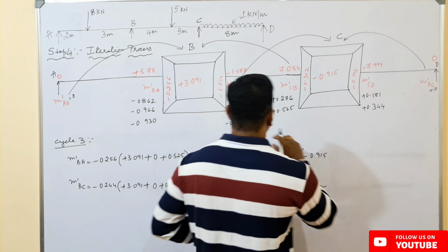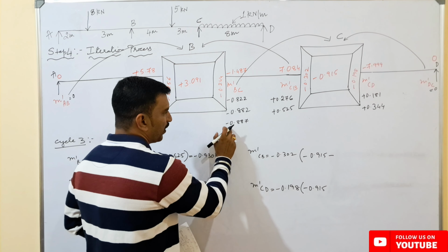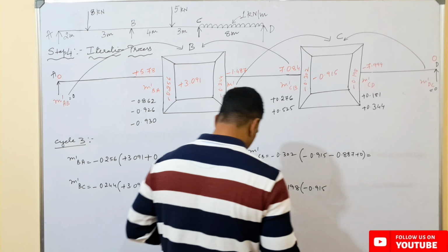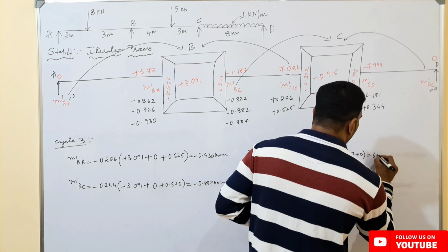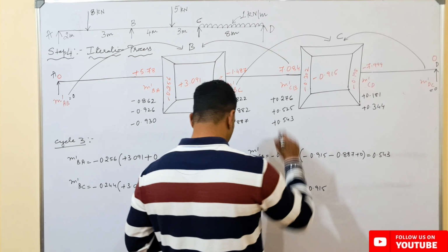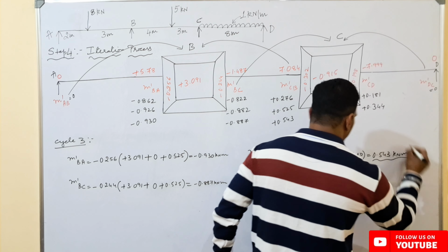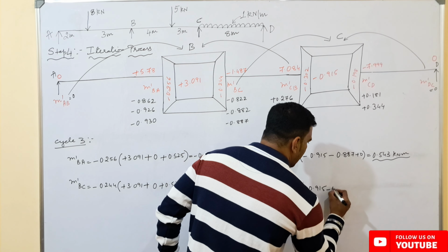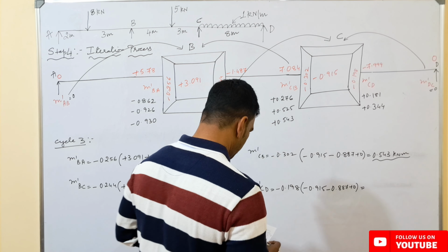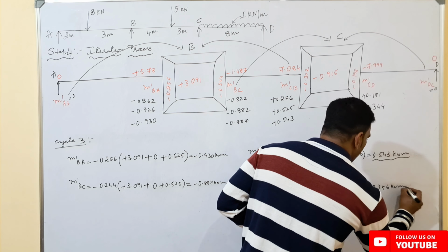In this we have a value, which is the summation of far end rotation contribution here. How much? A new iteration value here, this value minus 0.887 plus 0, which will be equal to 0.543. So this value we will write here, plus 0.543 kilonewton meters, and here it will be minus 0.887 plus 0, which will be equal to plus 0.356 kilonewton meters.